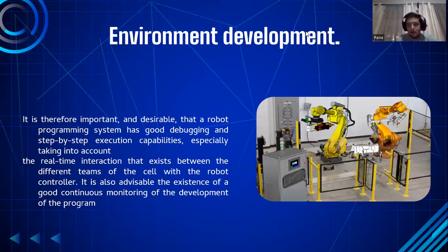The programming of the manipulator is complicated because the manipulator has interaction with the environment. This is the main reason why most robot programming systems are of the interpreter type, being able to carry out the step-by-step follow-up of the program at each moment.